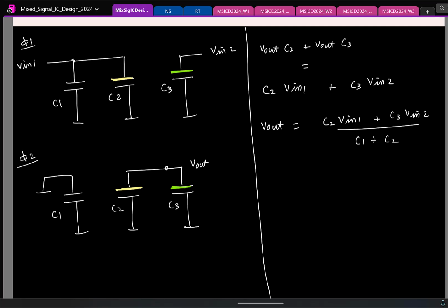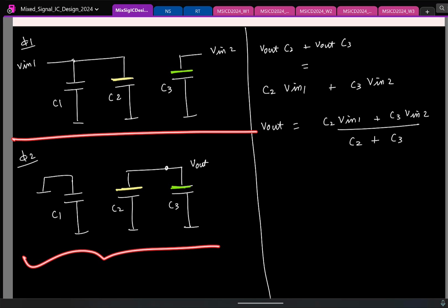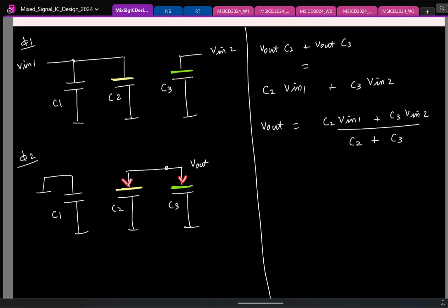Oh sorry, yeah, okay, thanks. Again, to make sure you are all paying attention, I made an intentional mistake. So as I was saying, sometimes the typical confusion is, why should I not take only C3, right? Remember, you look at one particular circuit, apply KCL there, which means delta Q flowing in both the capacitors is 0. So if there are 2 capacitors connected here, you look at the same capacitor charges in the previous phase. Clear?